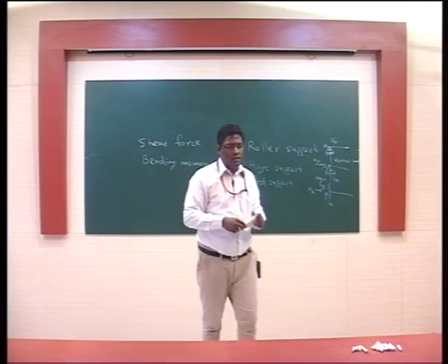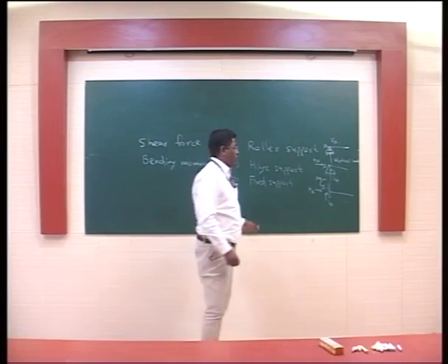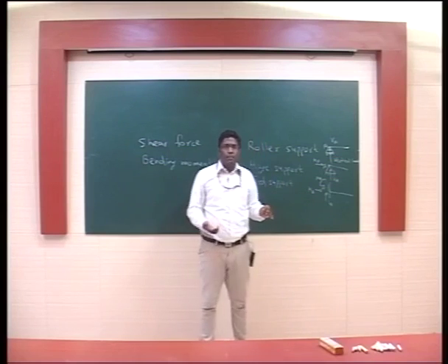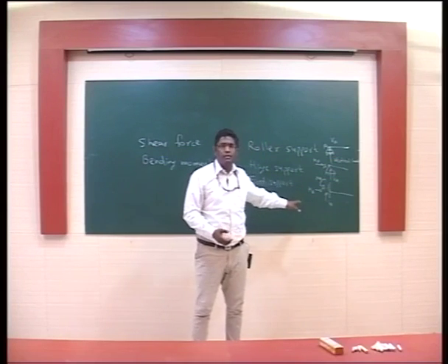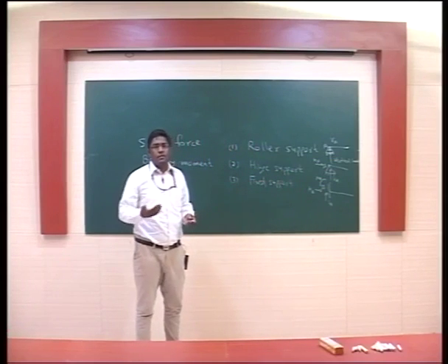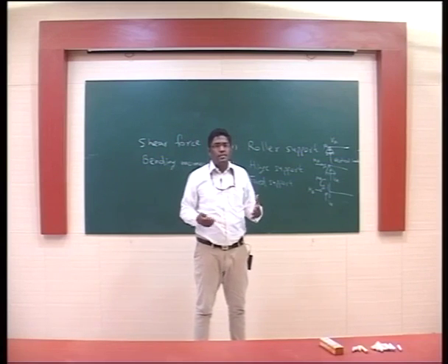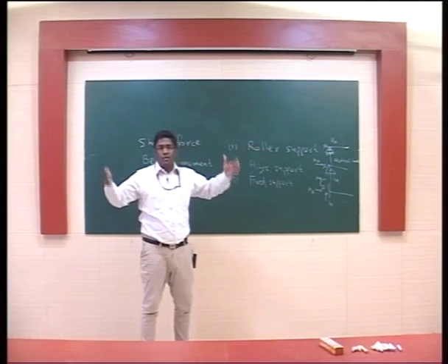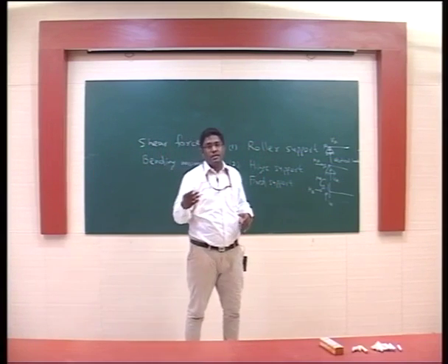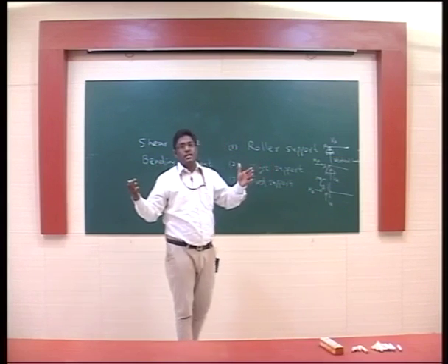Now for a civil engineer, what exactly are the implications or where we see these supports? In reality, in our structure or in our construction, we don't have hinge supports, but mostly we have fixed supports. But still, for the analysis purpose, if the work is done by stone, that means if the walls are created by stones, and then if there is an RCC slab or RCC beam there, then those particular beams are analyzed as hinge supports.